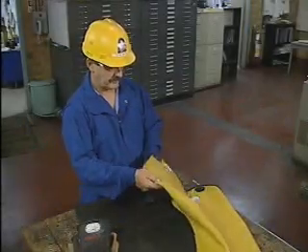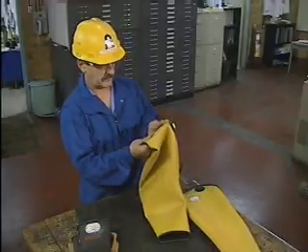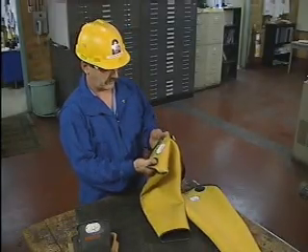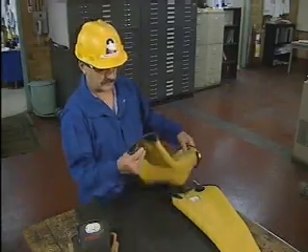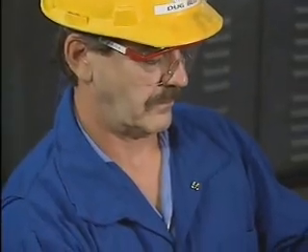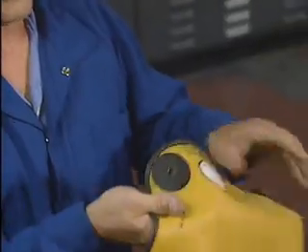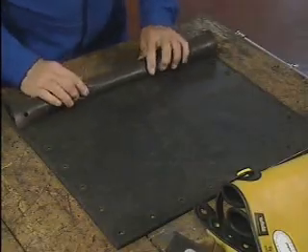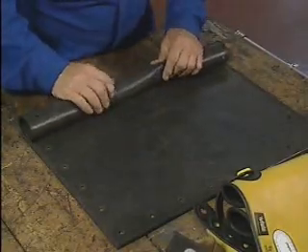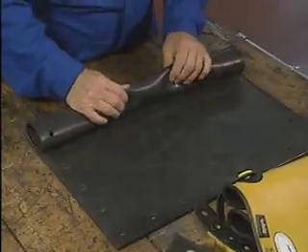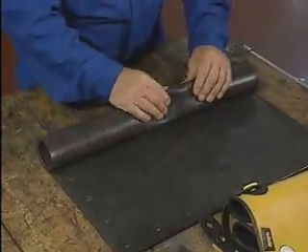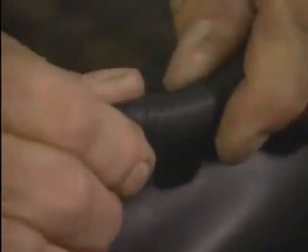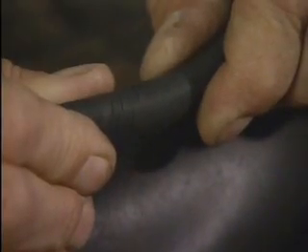It's usually a little more difficult to thoroughly inspect rubber sleeves and blankets than rubber gloves because there's no easy way to inflate them. The best thing to do is to examine the rubber as carefully as possible to make sure that there are no obvious cuts or punctures. A good way to do this is to roll the material tightly, which stretches the rubber. Then carefully examine the rubber material where it is bending. That way, it's easier to detect any small cracks or holes that might otherwise be missed.